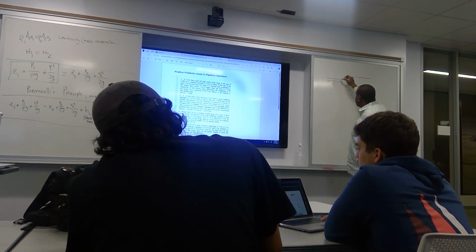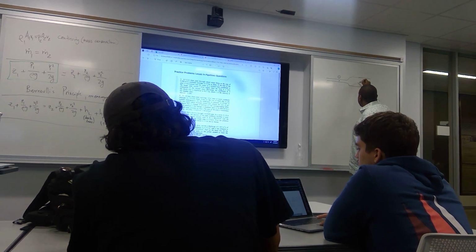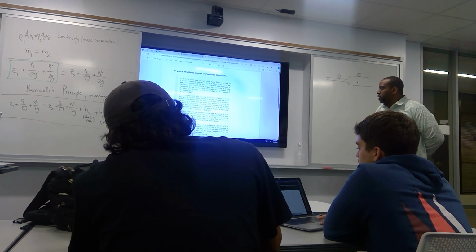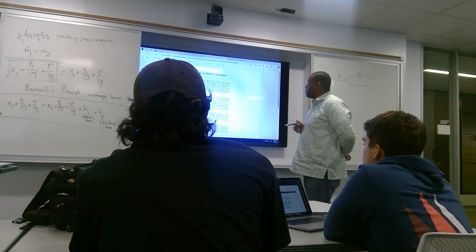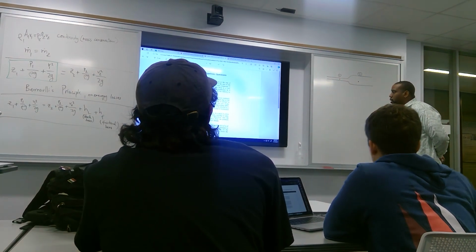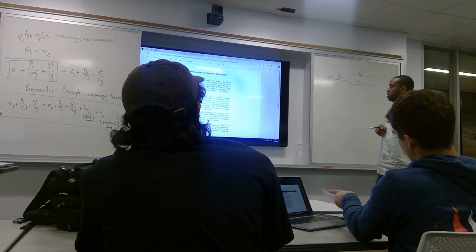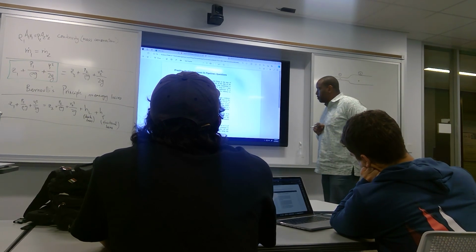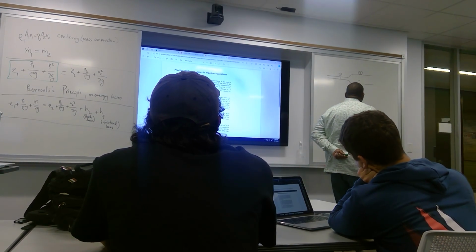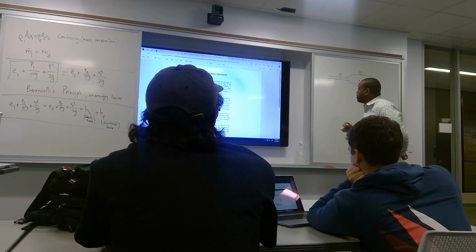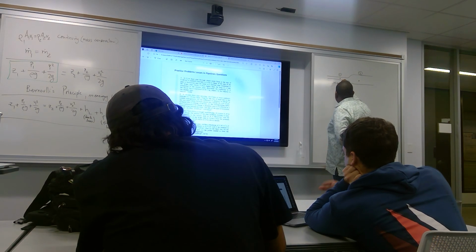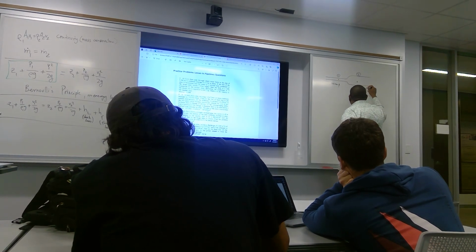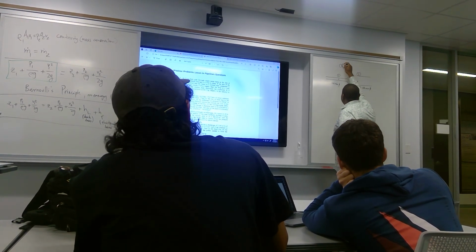So if we call this point 1 here, and somewhere point 2, because we're going to have some disturbance inside that area. Then find the corresponding difference in pressure if the change in diameter were effected by a gradual cone, assuming no loss. The axis of the pipe is horizontal. So we're told number 1 has a 100 millimeter diameter, and number 2 is 150 millimeter diameter.